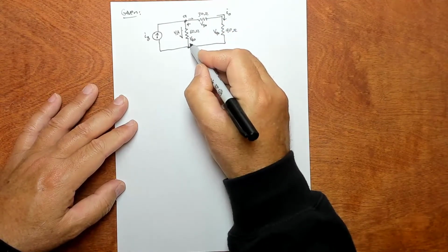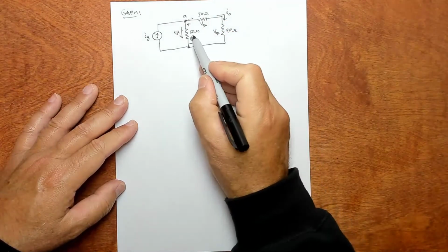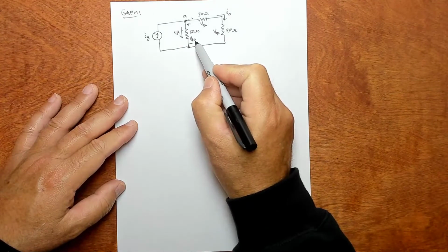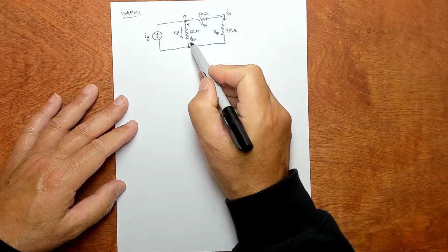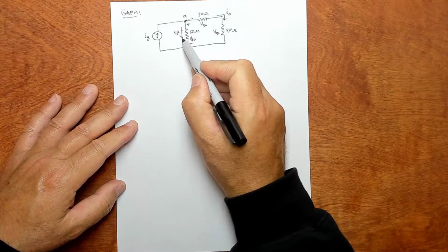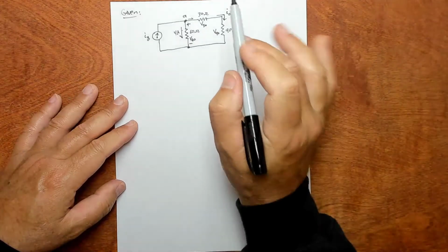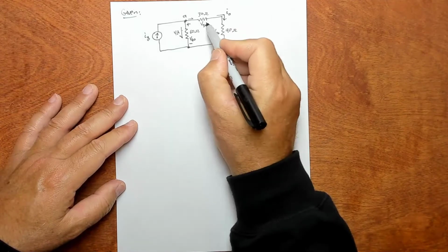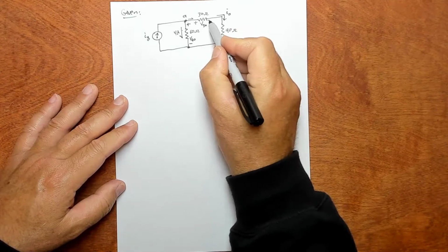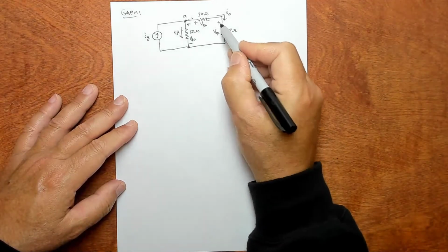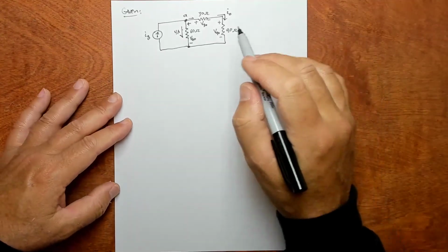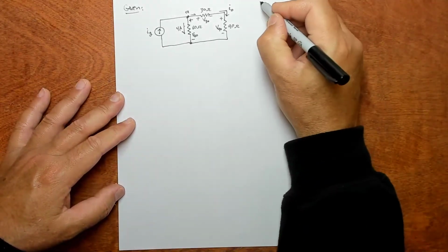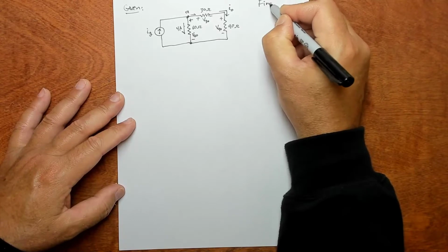So now we have the current polarities, and these are resistors, so we know that the voltage is going to be fighting those currents. So this V60 voltage is going to have this plus minus polarity in relation to the current, because that's just what resistors will always do. Likewise, if I sub 0 is going this way, then this V30 will have this plus minus polarity here, and V90 will have this plus minus polarity. All right? So you got to set that up, and then that's what's given.